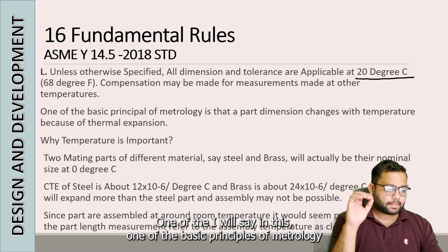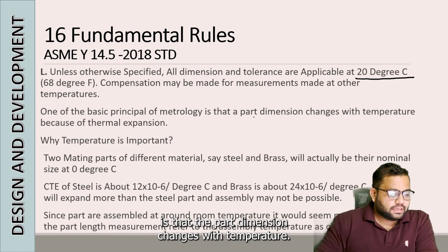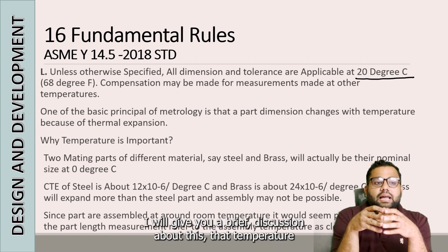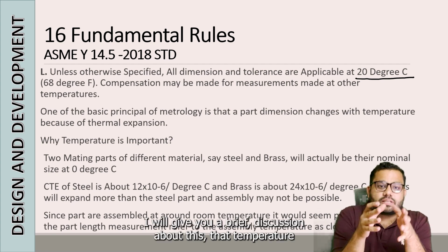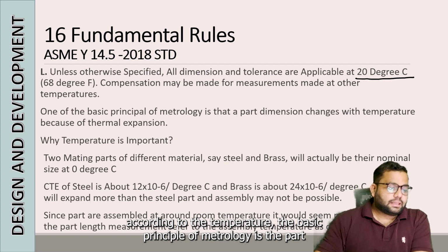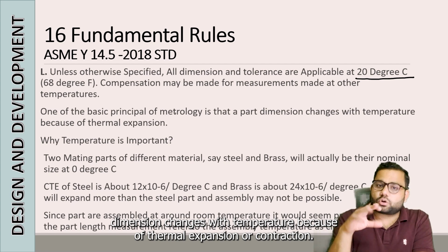One of the basic principles of metrology is that the part dimension changes with temperature. Why is temperature so important? First of all, I will give you a brief discussion about this. The part dimension changes with temperature because of thermal expansion or contraction.